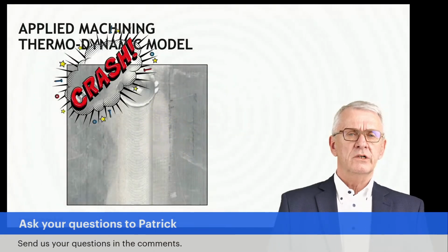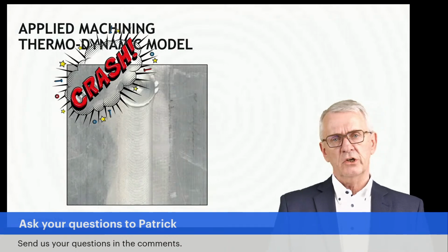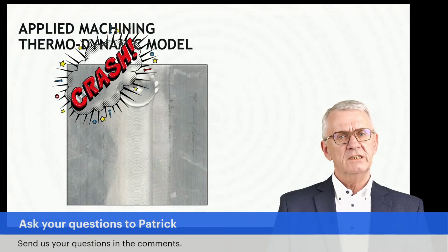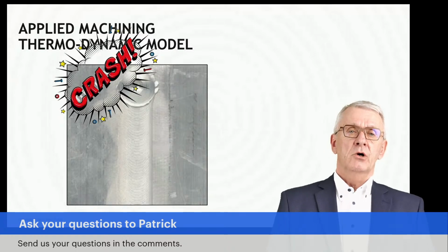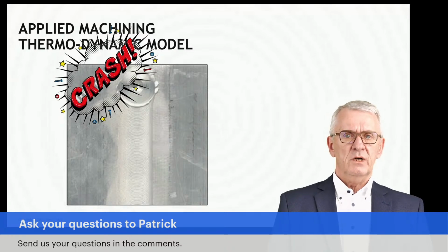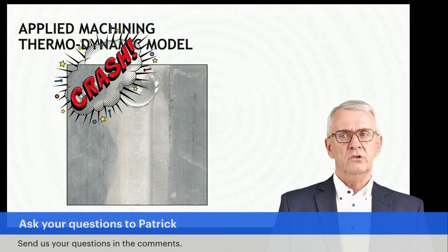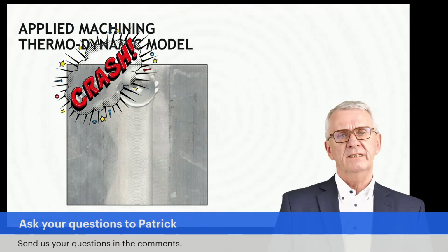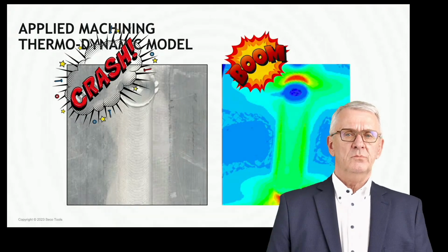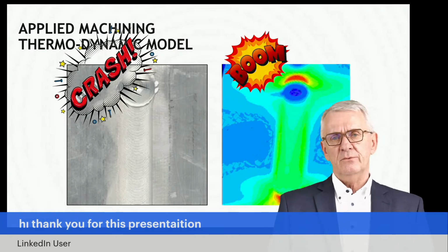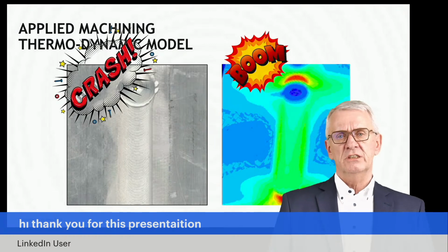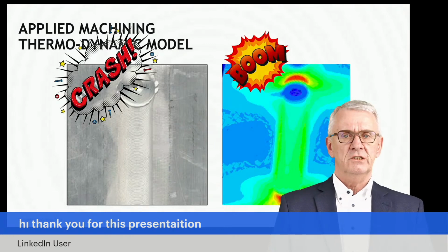And even more, because if you crash a milling cutter, or I should say, if you crash a cutting tool in general, people always think in terms of, oh, I lost my tool and I need to buy a new tool and so on. Some people are aware of, yeah, but what about my workpiece? Hopefully I didn't lose my workpiece, but also there, bear in mind that the consequences of a crash are not only mechanical, but could also be thermodynamic, because during a crash, the heat which is generated and the temperatures to which it leads create different types of situations.